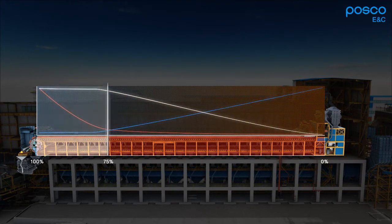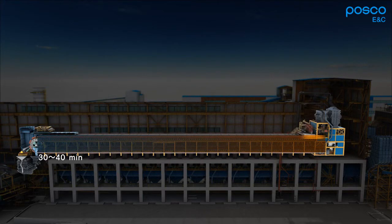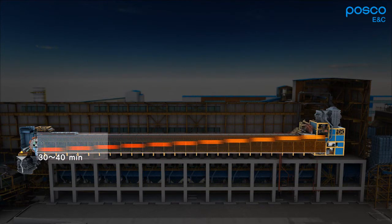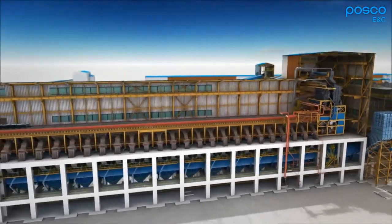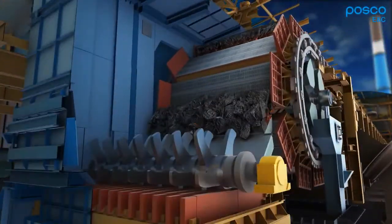This stage is called BTP in the sinter plant, and the sinter ore through BTP is not burned any longer and is discharged, going through a cooling process. It takes about 30 to 40 minutes for the combustion layer on the top to go down to the bottom, and the pallet passes through BTP and reaches the discharging outlet. The sinter ore burned in the sinter machine is combined into a pallet-shaped one which looks like a large cake.